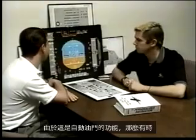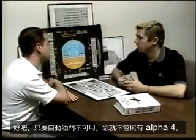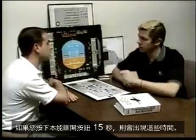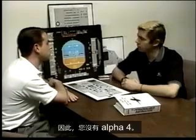Okay, since it's a function of the auto throttles, what are some times that alpha floor might be inhibited? Well, anytime the auto throttles are not available, you're not going to have alpha floor. Those times would be if you've pressed instinctive disconnect for 15 seconds. If you go into N1 mode, you don't have auto thrust, and therefore you don't have alpha floor.